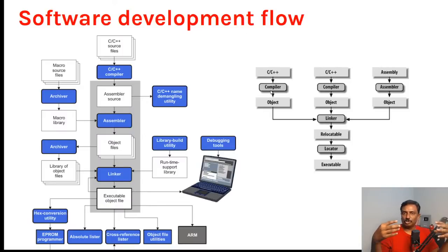So the compiler will give you the object file. You give only the object file to a linker, and to the linker you have to give a file called the linker description file, which I will be explaining in the next slide. That will differ from manufacturer to manufacturer, so different for microcontrollers, but the concept is the same. Once you learn it, you could modify it. It looks like C programming, but it's a different style of programming. But you have to write the linker description file.